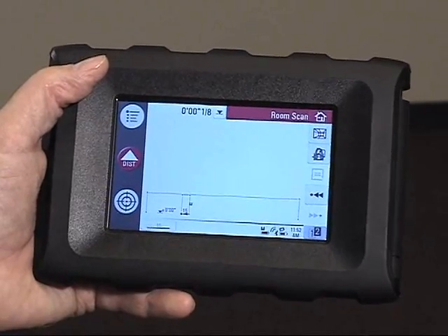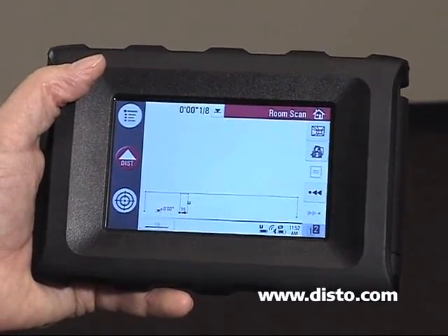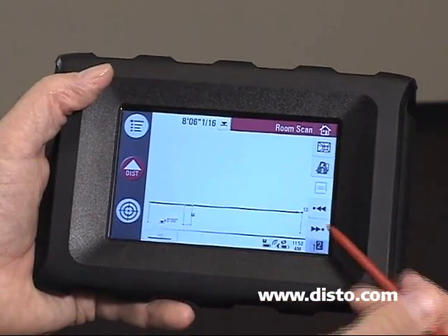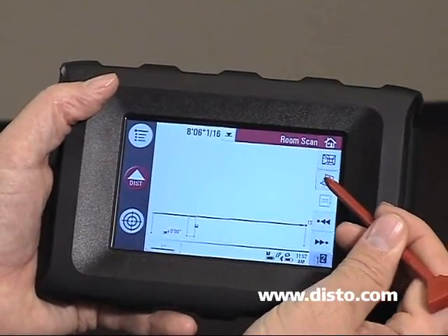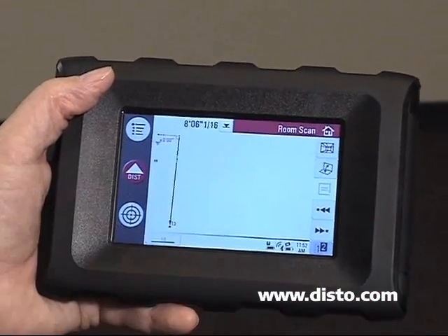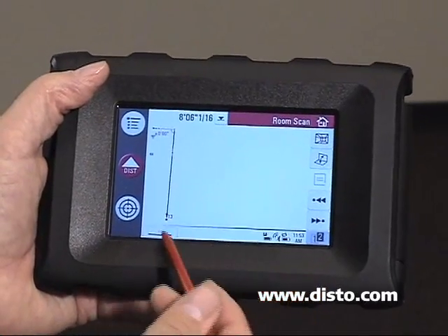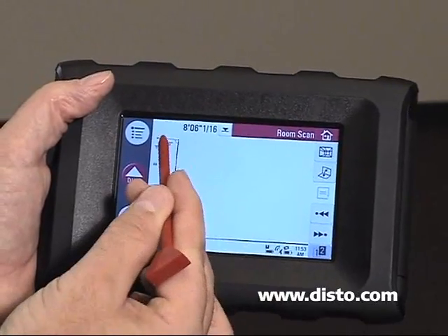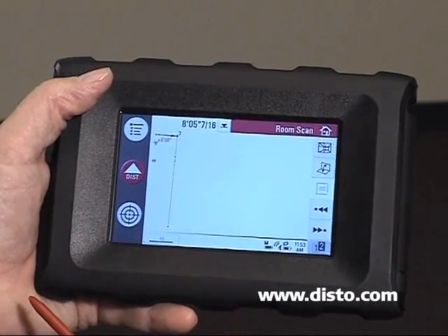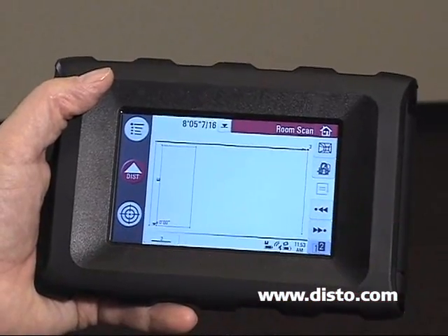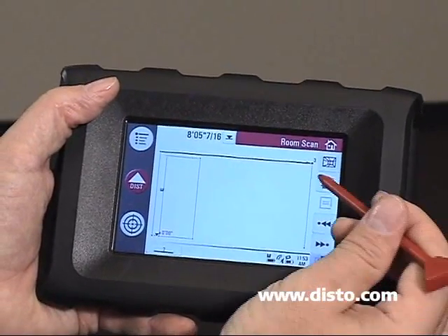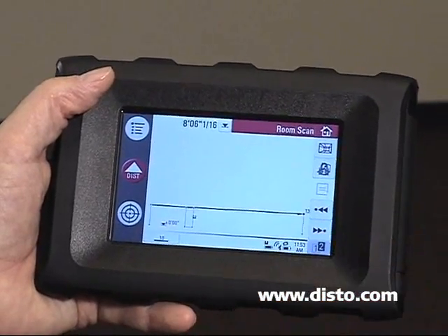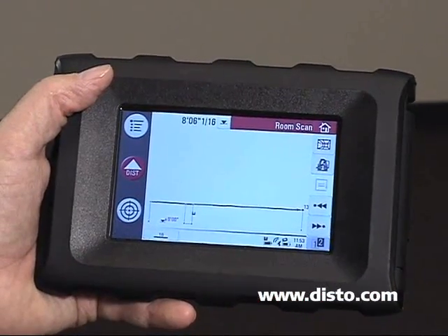We would do the exact same procedure to locate additional doors, windows, or other items of interest as we worked across that wall plane. If we unfold our section, I'm going to hit that top line again because I want to fold it back up. You can see that there's the first section that we had done earlier. Here's our second wall plane. Now it's pretty small because right now it's scaled so that everything fits into the view screen. I can select on that first wall segment that we had done at an earlier time, unfold on that, see the door located in that segment, fold it back up again, hit our new line segment and our new wall plane, unfold on that segment, and see the new door located in that segment.